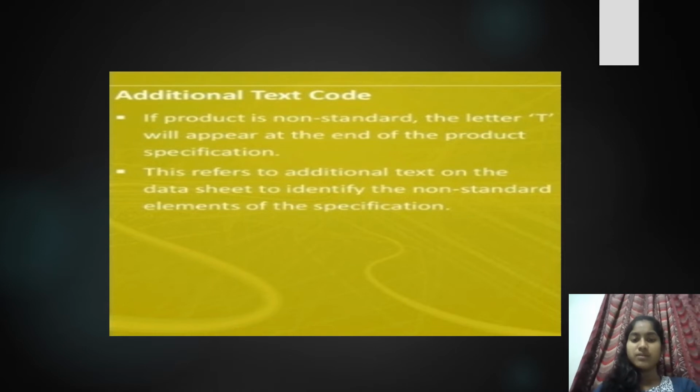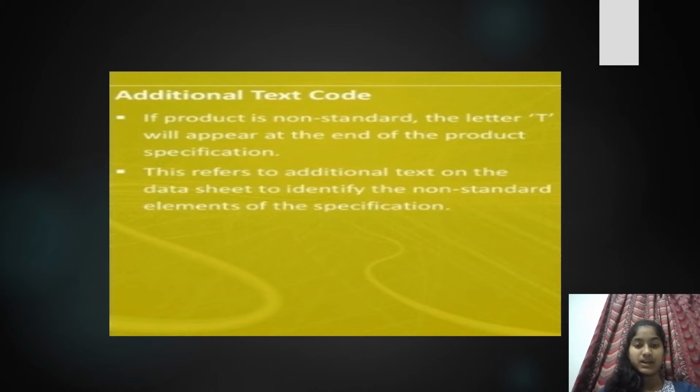The amount by which the crystal frequency can be pulled depends upon a variety of factors, including the level of capacitance applied, the circuit conditions themselves, and the crystal. However, the frequency cannot be pulled too far because the activity of the crystal reduces as the level of capacitance across the crystal increases.